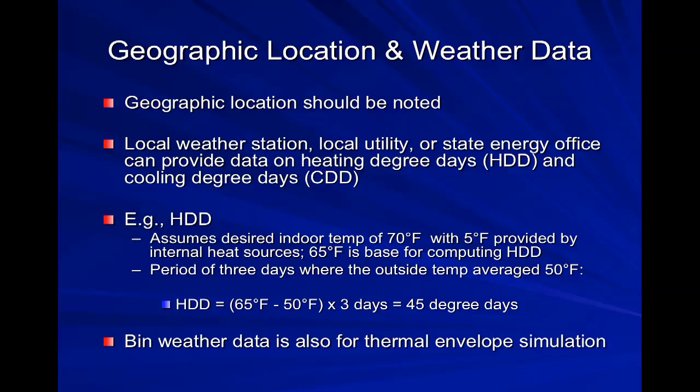In this example, the period of 3 days where the outside temperature averaged 50 degrees F, we're going to see that the heating degree day formula would be 65F minus 50F for 3 days. That would be 45 degree days.